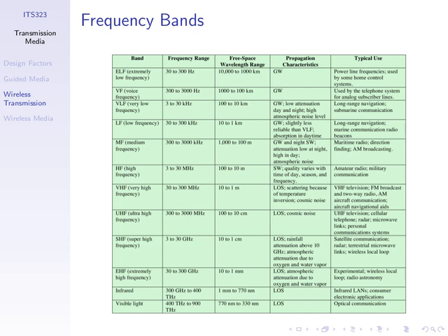There's another diagram at the start of the lecture notes. This one has it. VHF, very high frequencies, just the name of the band. Frequencies from 30 megahertz up to 300 megahertz. UHF is from 300 up to 3 gigahertz, 300 megahertz up to 3,000 megahertz. Ultra high frequency. So it's just referring to the range of frequencies used.